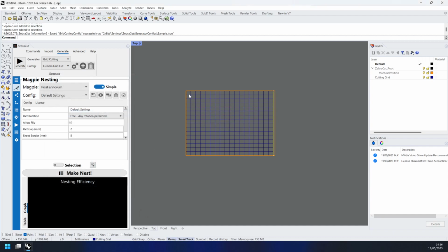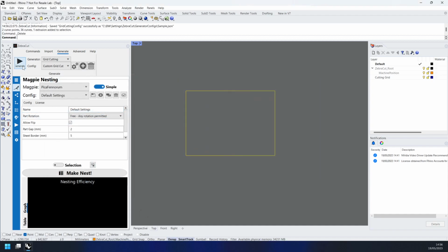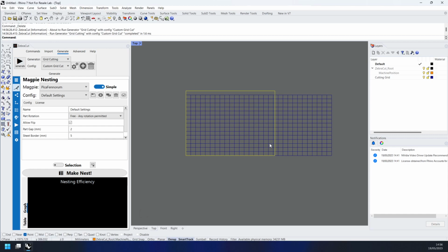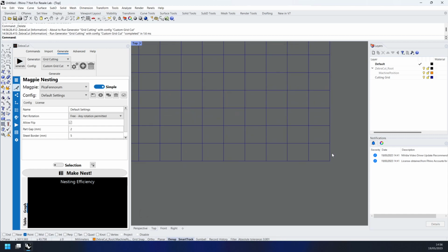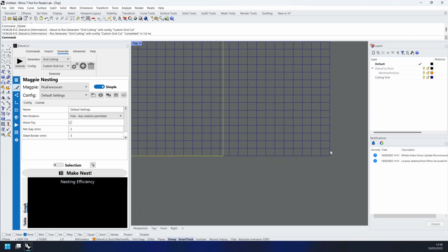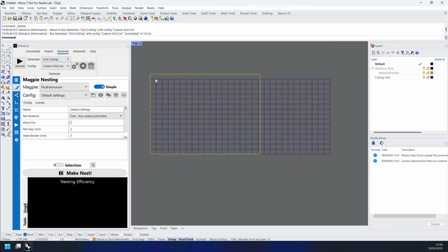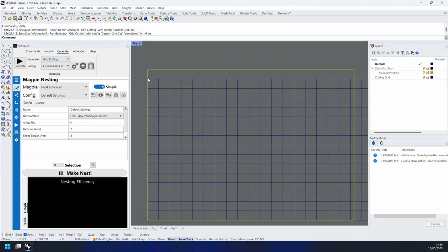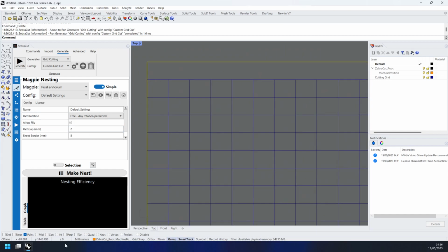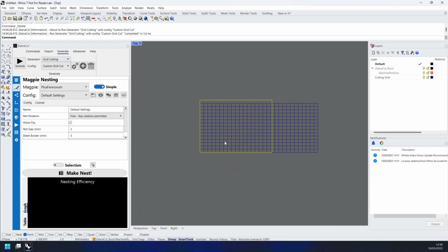So again, I'll just save that, delete the previous one, and then hit generate. And you'll see here now this has stopped right here. I think maybe I don't have enough columns there. That stopped at 3 meters, 3.6 meters. But the Y, for example, has stopped. You can see down the bottom here the Y. We've stopped at about 1500 millimeters as required.